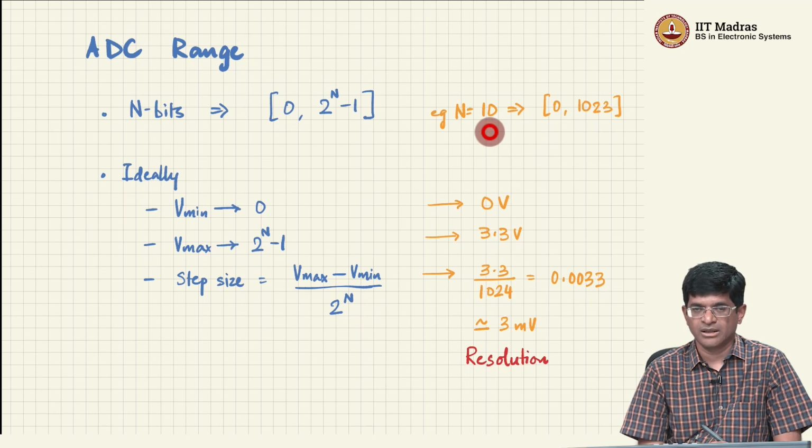That's not good enough, because there will be physical noise associated with the system, there will be noise in your amplifier, there will be noise in your analog circuits, there will be non-linearities or non-idealities in your A to D converter, all of which add up and tell you that it doesn't matter if you put 20 bits over there, only 10 of them actually make sense, okay.